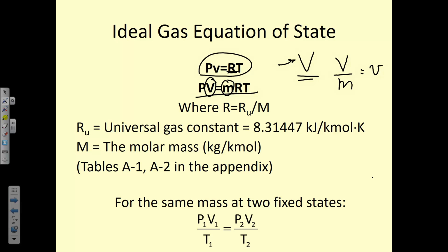And again, it's very important to keep track of units in your equations so that if you do accidentally use the universal gas constant and you've got kilomoles in your equation and they don't cancel out anywhere, you know you've done something wrong. Okay, so keep track of your units at every step of the process and don't just get to the end and say, okay, that's probably kilograms, because that's what I was going for. It's an additional way to check yourself and make sure that you're doing it right.